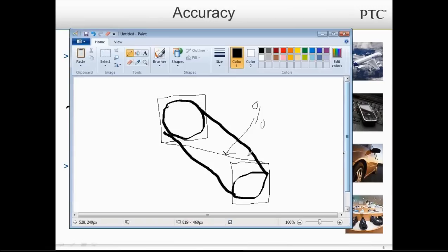Now, one of the major reasons that PTC did this, and honestly I've seen grumblings about them removing this, is that a long time ago, when computers weren't nearly as powerful, the more math and work they had to do with much larger parts, the longer it took to regenerate them. So the more features, the more surfacing, and the larger the parts, they dumbed down the part so it made regeneration easier.